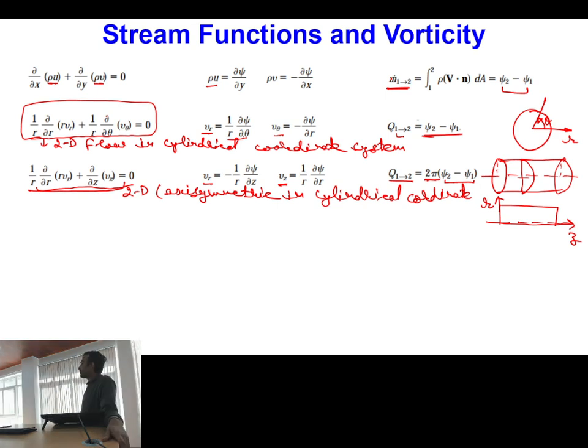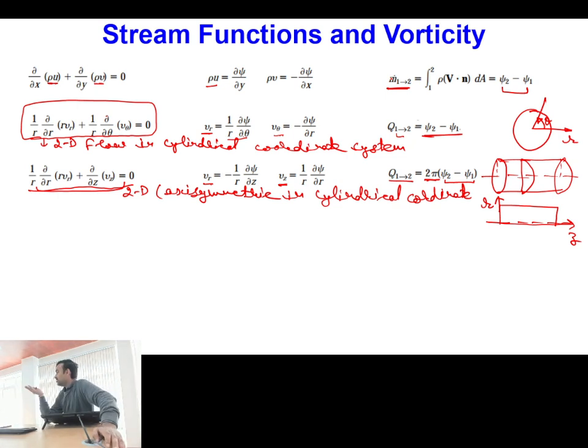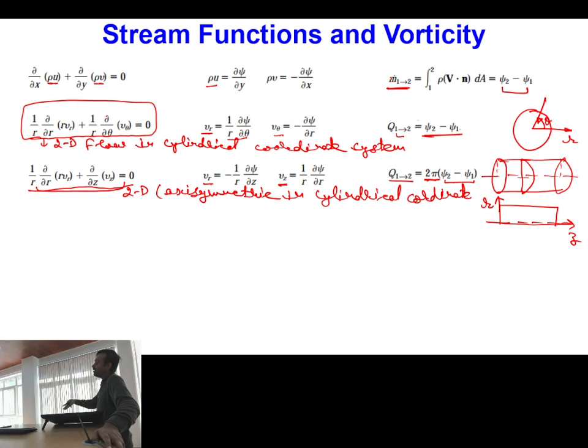When we find a discharge stream function, the flow must be rotational? Flow must be? Rotational. No. It can be applied for other situations as well. So flow must be irrotational will be applicable once you are talking about the potential function. Whenever we take the assumption that curl of velocity is equal to 0, this is a mathematical situation which can be satisfied if the vector field can be written in terms of the gradient of another scalar function. So that is the potential function. So the potential function will be defined only if my flow is irrotational. So the stream function can be applied for any situation.